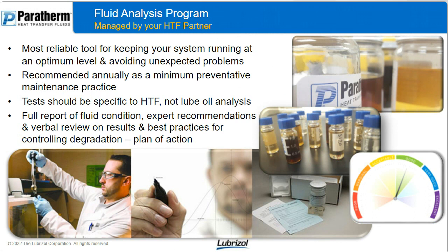If you're going to be changing fluids out, adding fluid, if you have any questions or any of these red flags in your head that we talked about previously, as an ideal user, you're always looking for red flags. You've recorded your readings, your exhaust stack temperatures. If any of that changes to the point where it's a concern, call your thermal fluid supplier, and maybe just getting a fluid analysis will either help alleviate some of that stress or justify the fact that your red flag was actually there, right? So you can tell a lot from a fluid analysis.